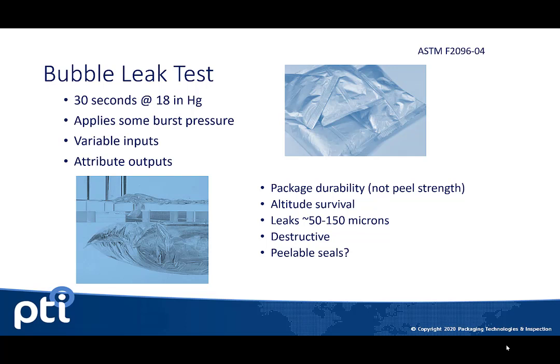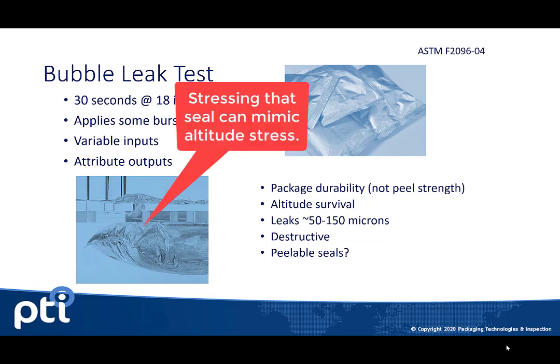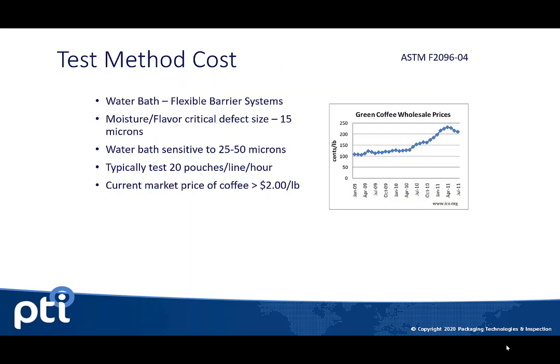So that is creating almost like an altitude leak test. And that's something we can mimic with another vacuum-based test. But the water bath is not able to go to deeper vacuums on a peelable seal. That's one of its limitations. So if you have a peelable cup or pouch, the sensitivity of the water bath is limited by the peelable nature of those seals. So we want to mimic a water bath, but before we do that, just know this: